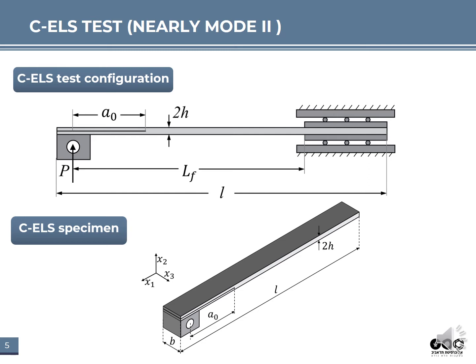The load is applied to the specimen through the load block by means of an Instron loading machine. The load block is pulled up vertically through a pin, and the clamping arrangement creates free horizontal sliding of the specimen by means of bearings, but it restricts vertical movement.